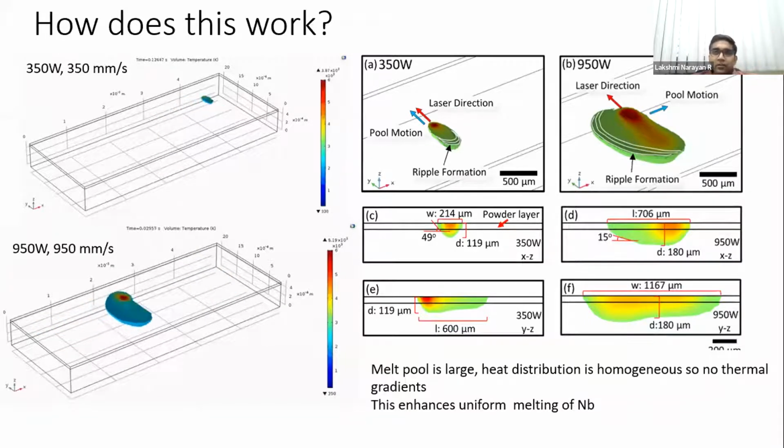So this kind of experiment tells you that just relying... If you had seen the earlier slides, I had shown you a picture that at moderate velocity, you will have a very bad single bead. A single bead is not very well fused. But if you run this for a whole build, you see that you are now getting a very good microstructure, which I will show you. The melt pool is very nice. You get very negligible porosities. Of course, zero porosities in terms of keyhole ones, but also very good melting, which means inclusions are very less.